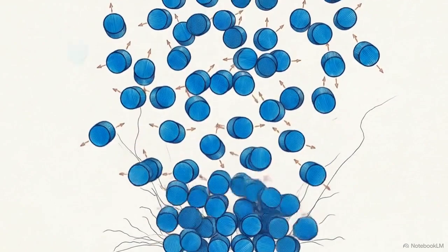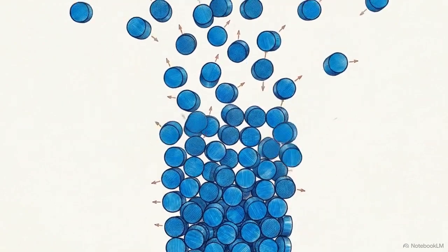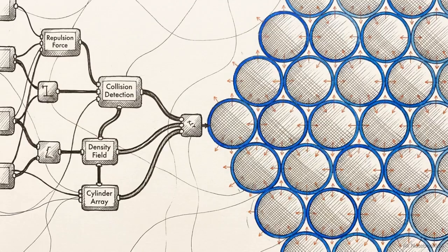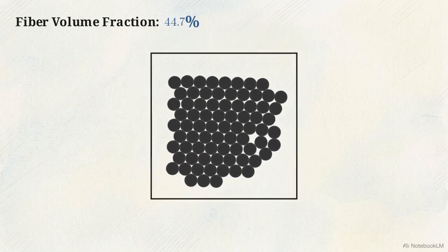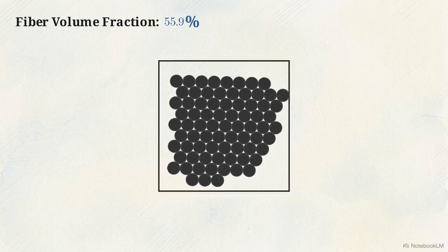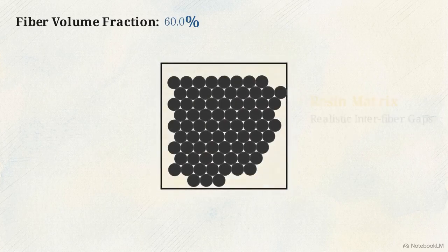We can use rigid body dynamics to digitally pack thousands of fibers into dense, mathematically controlled bundles. This image shows the limits of the hardcore model, where older packing algorithms like sequential absorption struggle at high densities. They hit a jamming limit very early, leaving the volume saturated with no room for new fibers. Modern workflows solve this using physics engines, such as Blender's rigid body dynamics, which applies simulated repulsion to prevent any fiber interpenetration. As the simulation runs, fibers act as physical cylinders. They shift and lock together into dense, non-overlapping distributions. This repulsion technique drives the volume fraction up to 60.